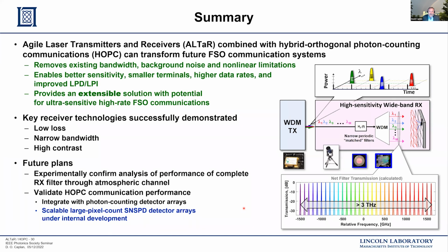I think the concern comes primarily from legacy RF systems, which have really wide beams and are easy to pick off. Optical systems are really narrow. The whole reason the beams used in free space optical systems are narrow is the primary reason why it's so efficient. Even with small aperture sizes, the diffraction angles are really small. So it's really hard to do that.